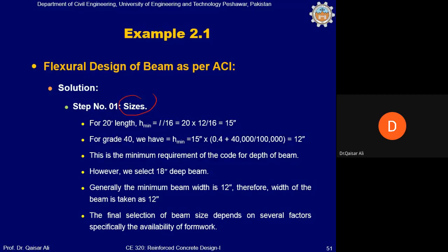every size. For example, you decide that it is very good from the calculation point of view to use a beam with the 13-inch width and let's say 17.5-inch total depth. So your calculation tells you that these are very optimized sizes, width of 13-inch and depth of 17.5-inch. But then this beam must have to be produced practically in the field situation.